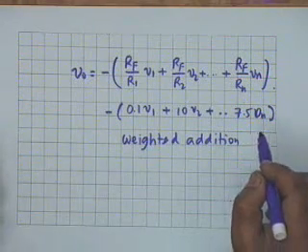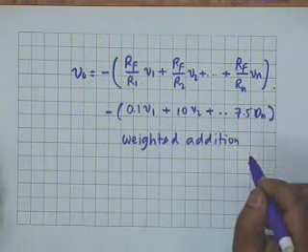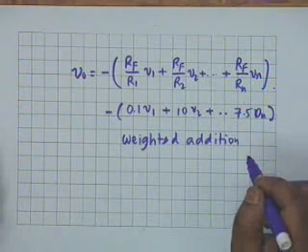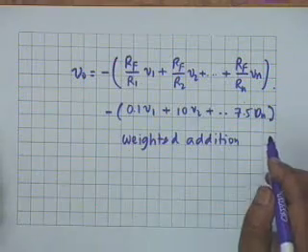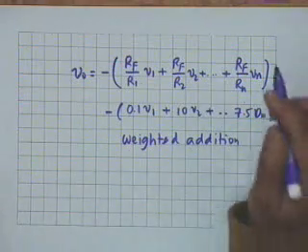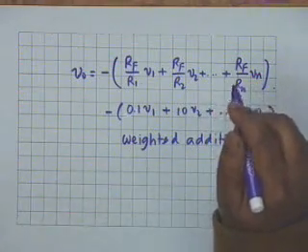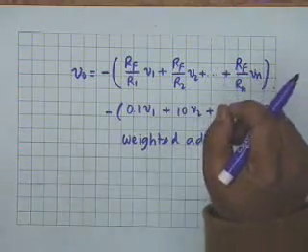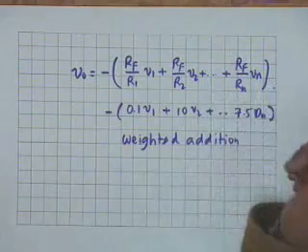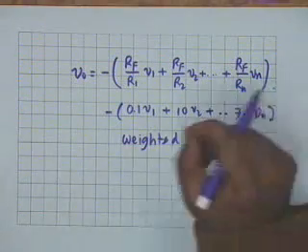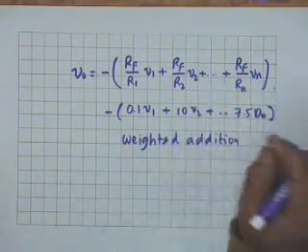Alright. What is the input impedance faced by V1, for example? R1. Similarly, each voltage source faces the resistance that is connected between it and the inverting terminal, that is the input resistance.